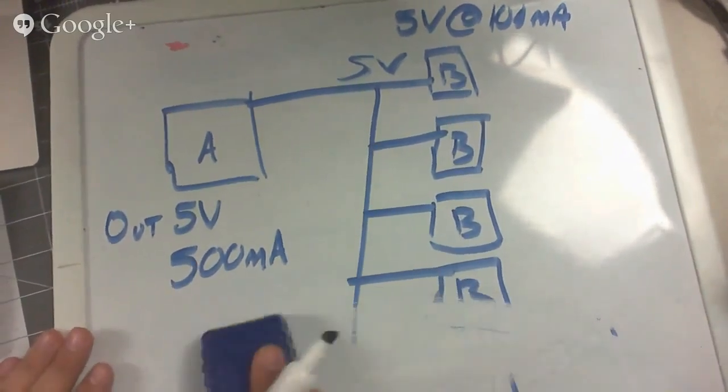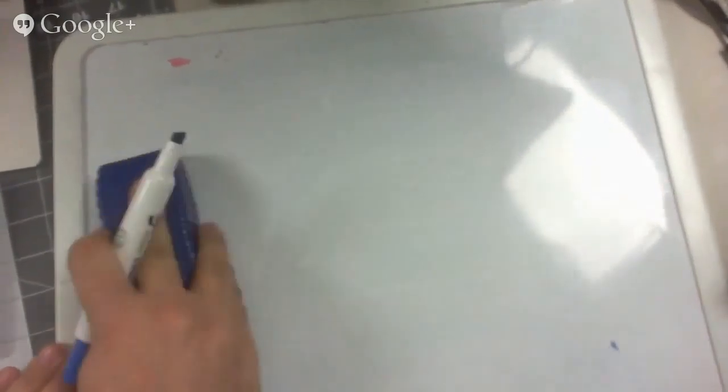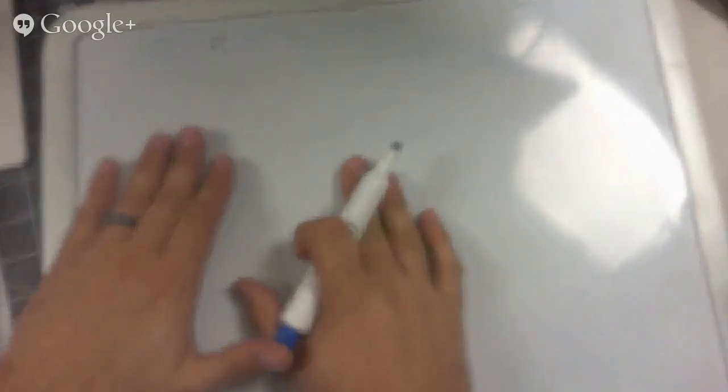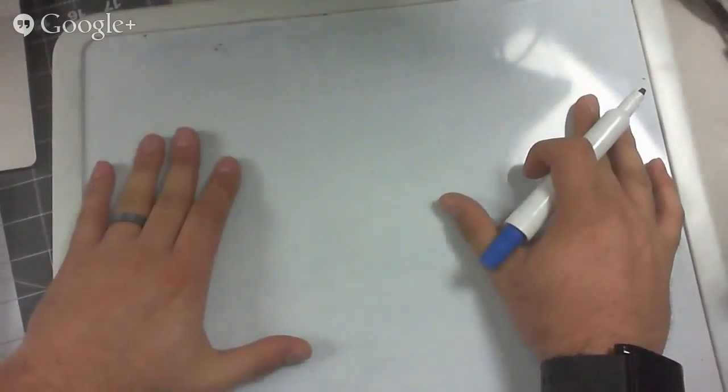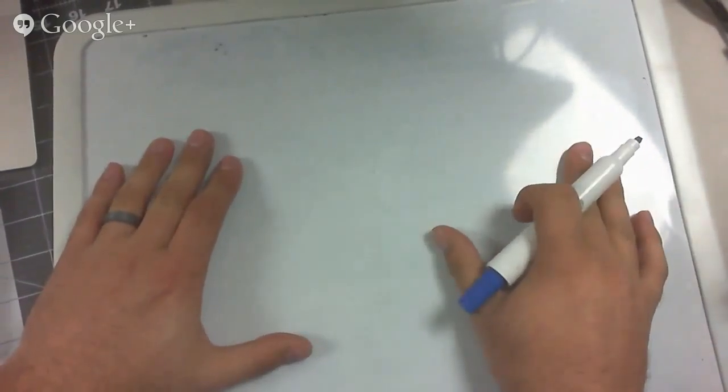So, long story short, always make sure that the voltages between two devices match, or you need to do some sort of circuit in between to translate between the two voltages. And there's actually chips that do that. For example, Arduino is 5 volts, Raspberry Pi is 3 volts. So things that were built for Arduino won't directly work with a Raspberry Pi without some conversion.